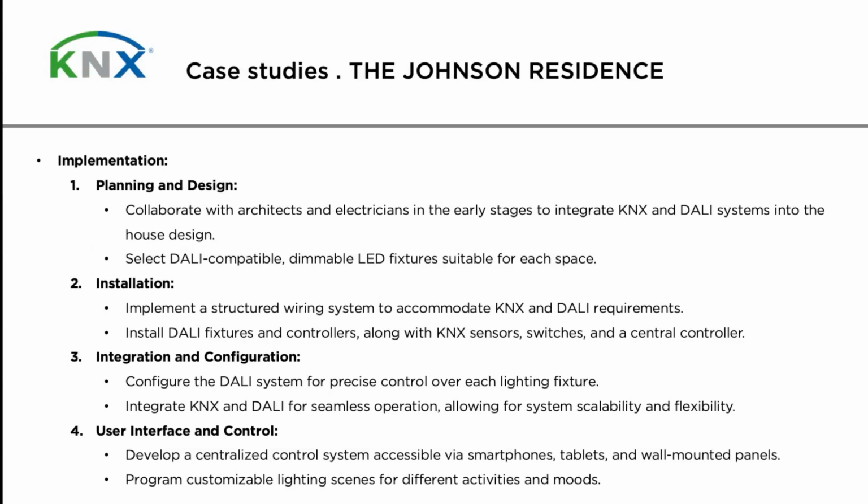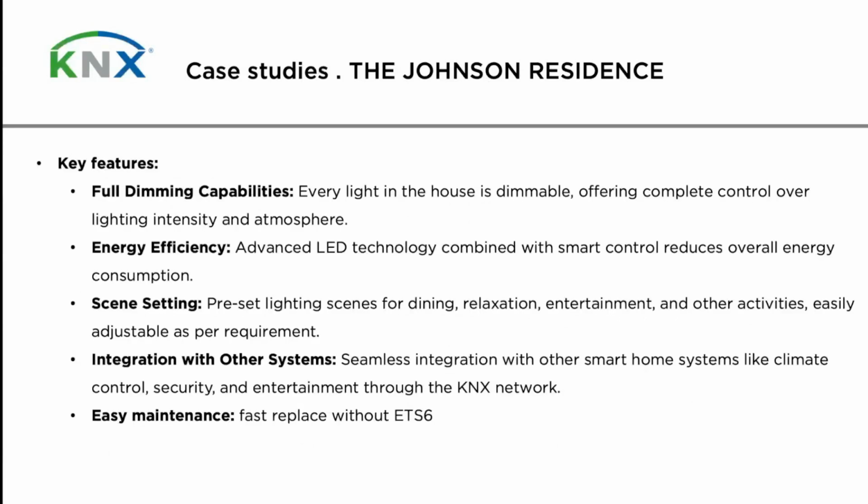So we choose the DALI compatible dimmable LED fixtures for each space. If we don't have one available, no problem, because we like some specific design, we go for that and we make them DALI compatible with an ECG. Full dimming capabilities, energy efficiency, scenarios, very important scenarios. In villas, in residential, commercial, we can have 120 lights.